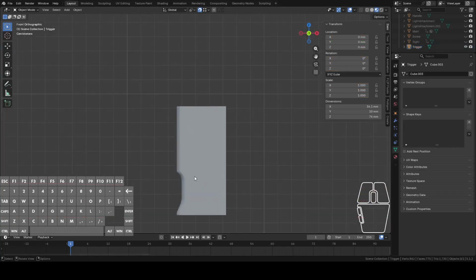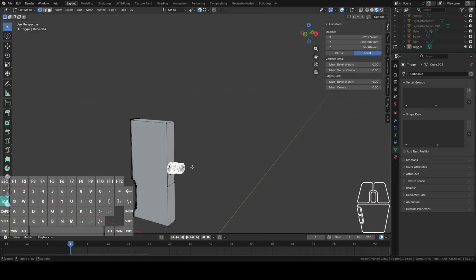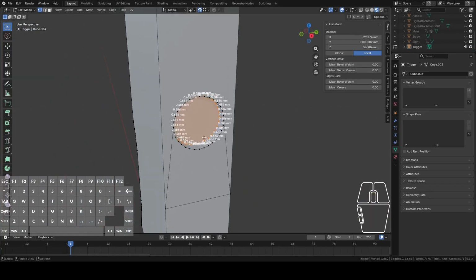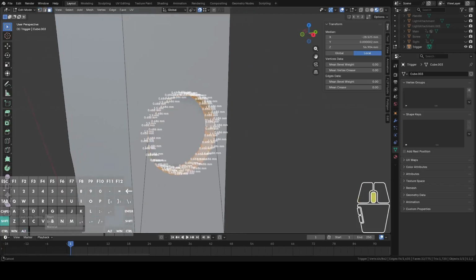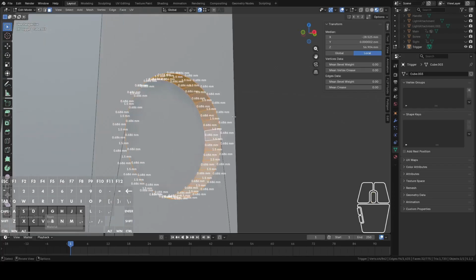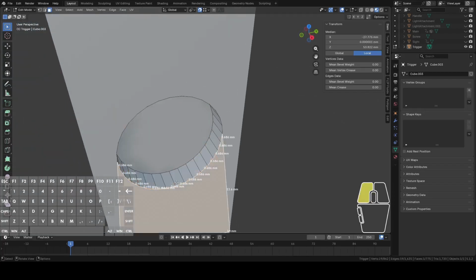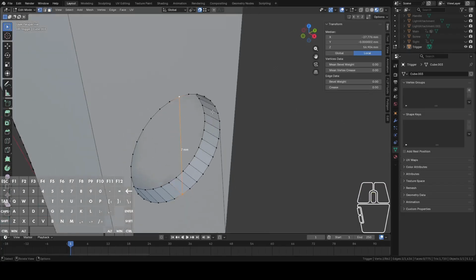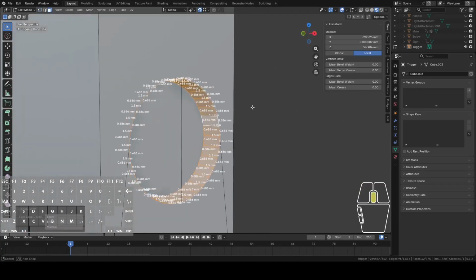And yet another thing, I was noticing the trigger's not sliding as gracefully as I would like it to. So first off, this spring hole might be just a little thinner, like fractions of a millimeter thinner, and I'd like the spring to slide a little more easily in there.